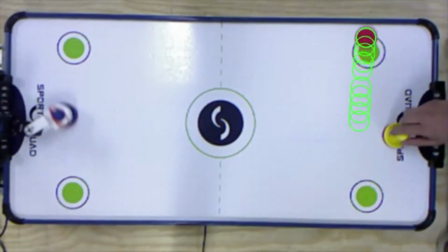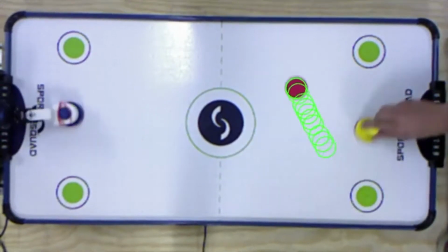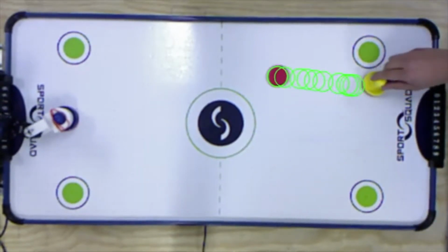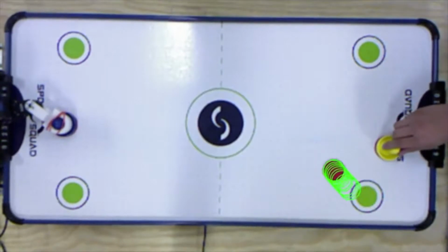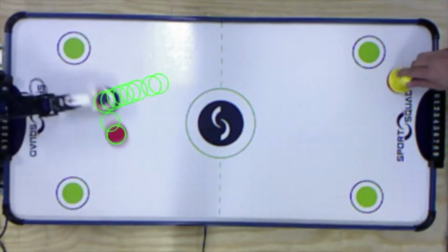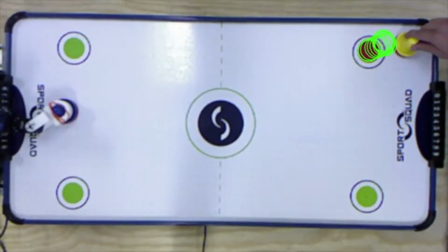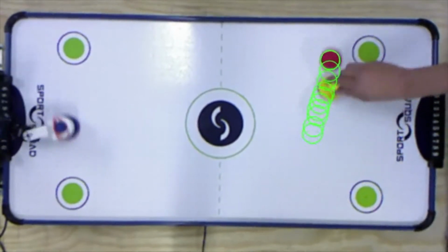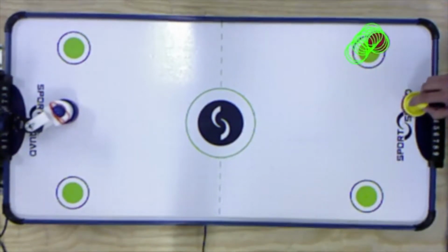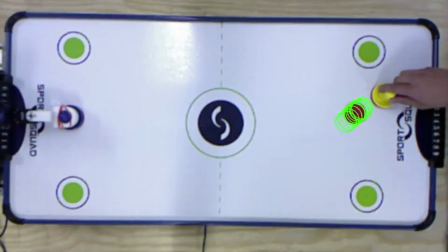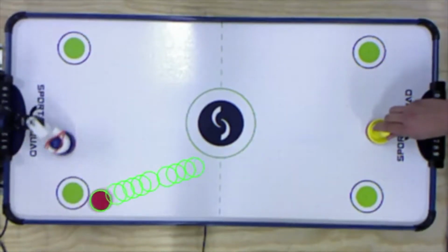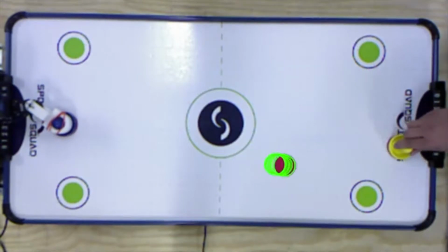From its position above the air hockey table, the Kinect sends frames to our CPU. In our code, we set a series of parameters like the color range and the area of the object we wanted to detect, namely the puck. Then, whenever we receive a frame from the Kinect, the image is passed through a binary filter that converts the color range we're interested in, red, into white, and all the other colors into black. Next, using the contrast between black and white, OpenCV reports the coordinates of the blobs with the right dimensions, as set in our code initially.